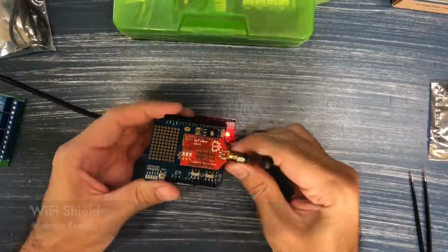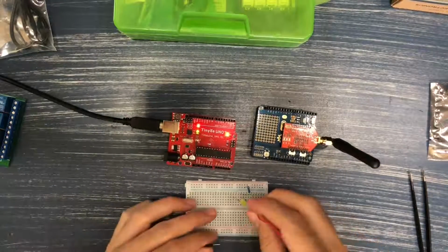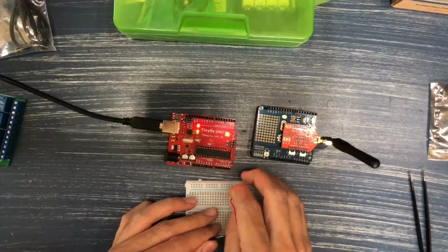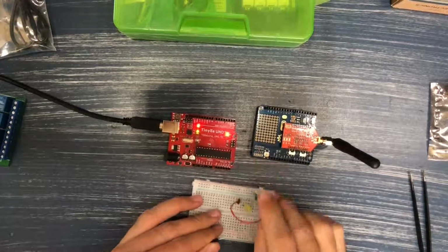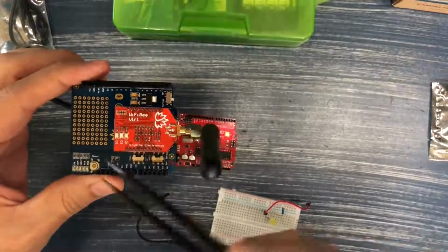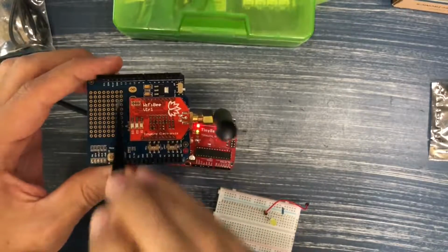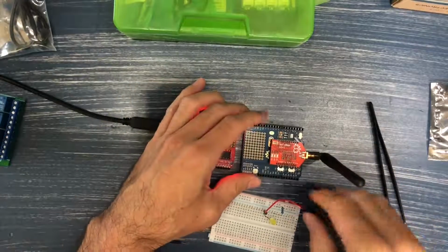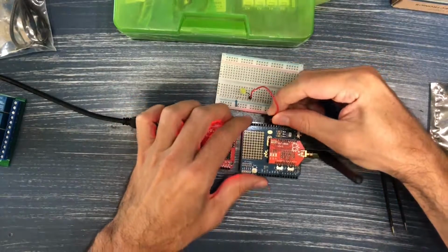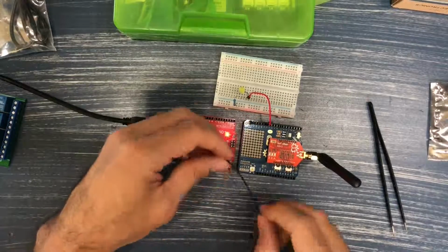So here is the Wi-Fi shield. This is very common. It's basically a prototyping shield that fits right over an Uno form factor. Okay, so we're going to be connecting an LED, and we're going to try to control this LED from our Wi-Fi shield. So let's do our regular wiring. This has the same pin out as the Uno, and pin 12 is where we're going to actually connect our LED. So instead of giving it 5 volts red, we're going to be giving it pin number 12. So only when we set the pin to high is it going to get power.